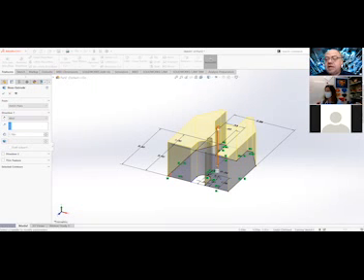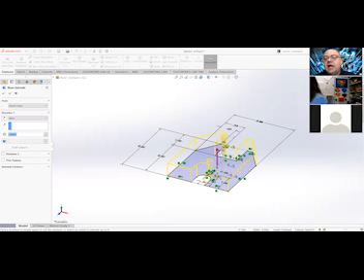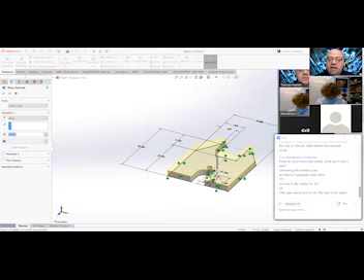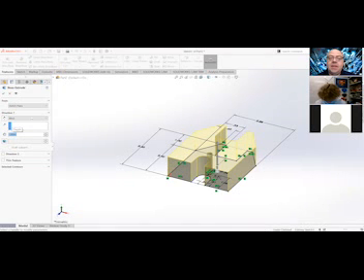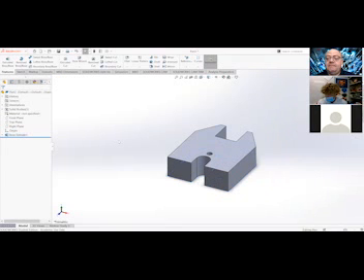So you can take this arrow and follow that virtual ruler and try and line that up to exactly 1 inch, which is nigh impossible. Or come over here to where distance 1 is, type 1 and hit enter. And when you get the 1 placed in there, you hit the green check mark and it's done. Oh, that's so cool. That's solid.